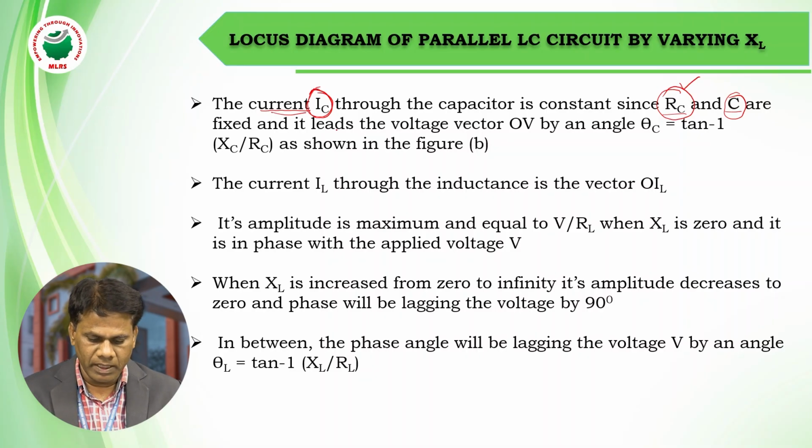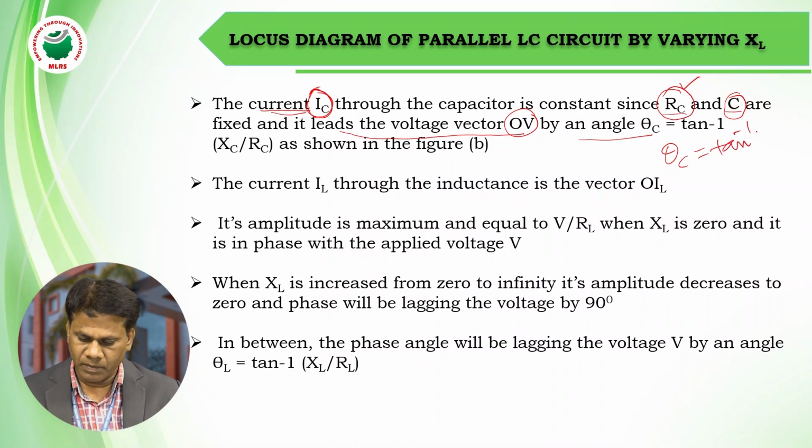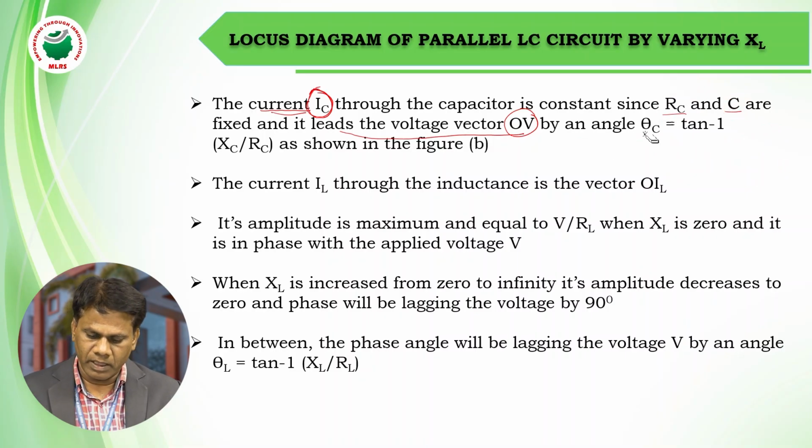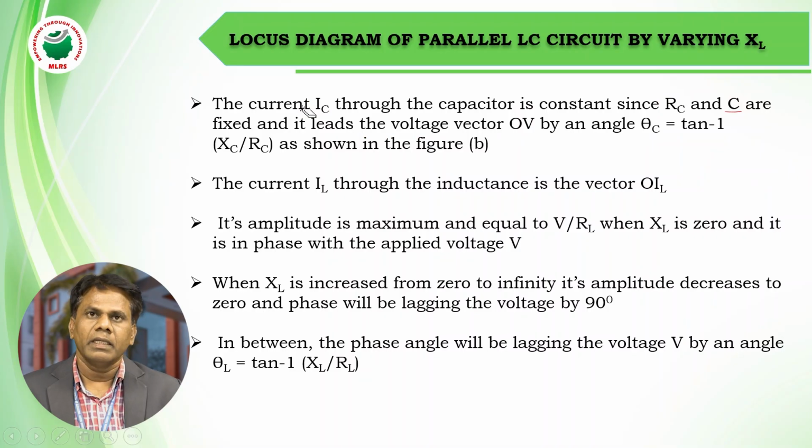This current leads the applied voltage vector OV by an angle of tan inverse XC by RC. Simply, in a capacitive circuit the current leads the voltage.